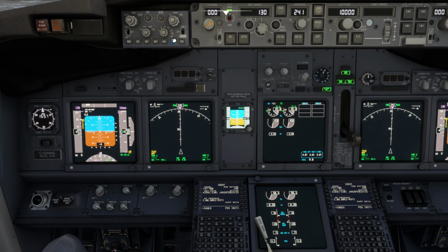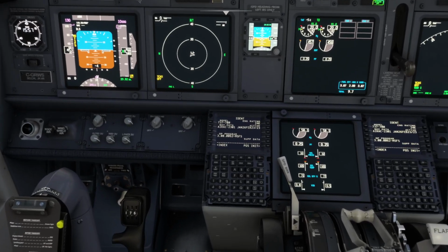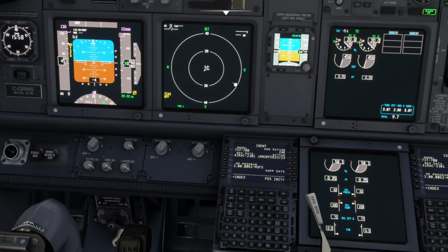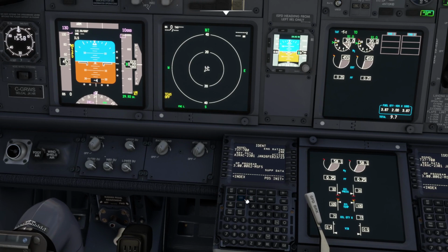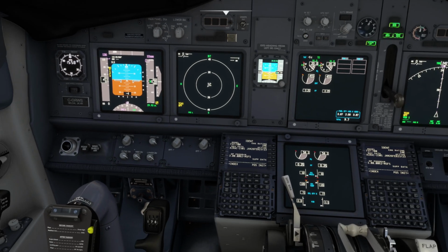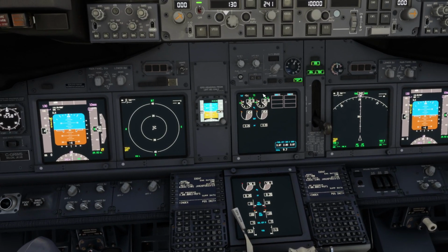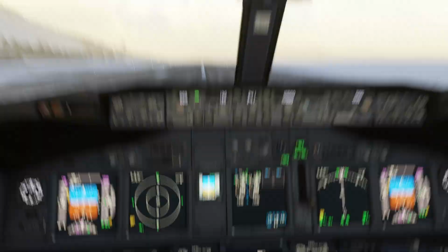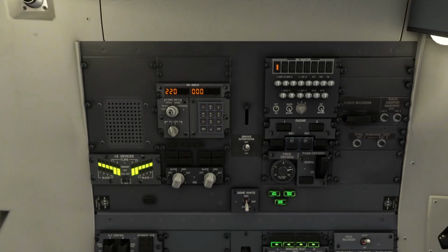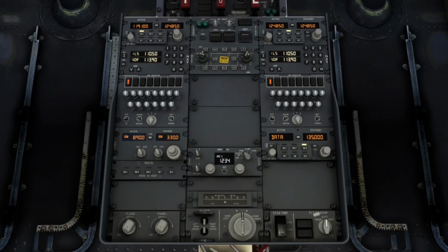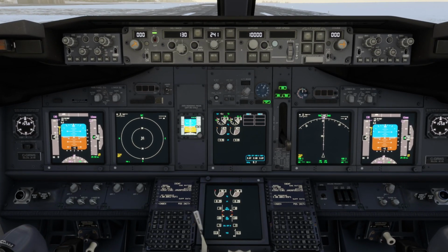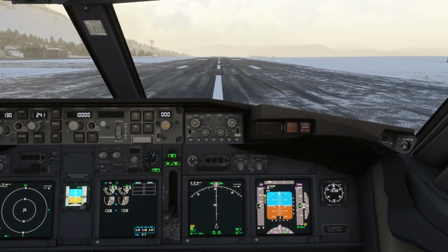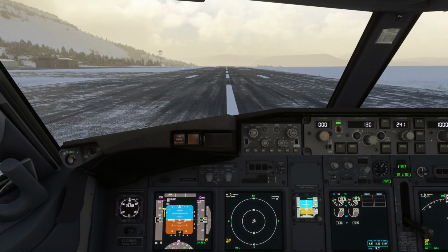And of course, if I'm working with the legs page and the plan view here, I can select plan view and then change the zoom that I want. And then I just zoom in and I can work with my FMC and my navigation display as well. So once again, at any time I need the aft overhead, number 9. Anytime I need the pedestal, number 3. Anytime I want to go to the center, number 5. Anytime I want to go to the right, 6. To the left, 4, and so on.